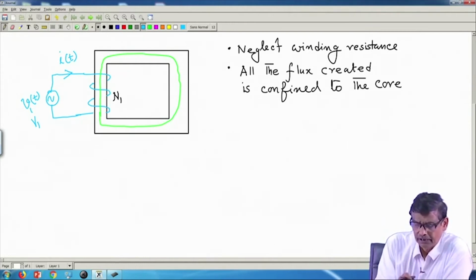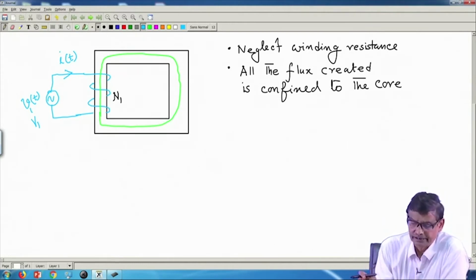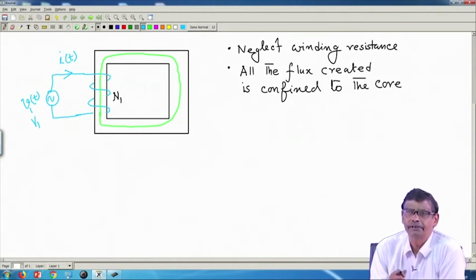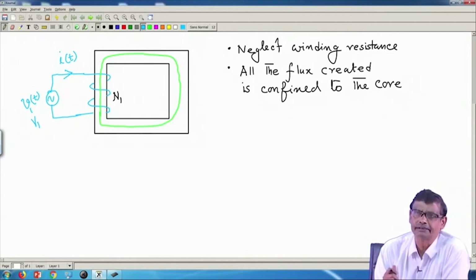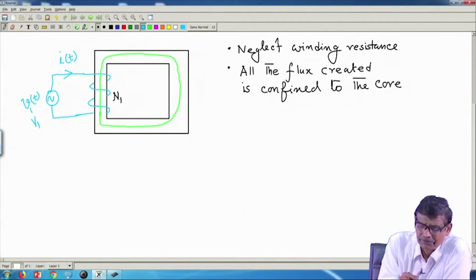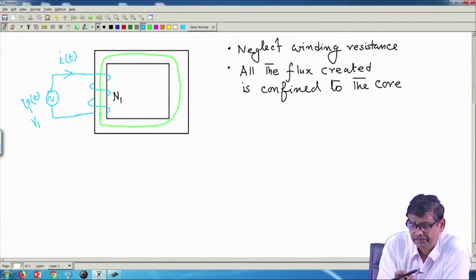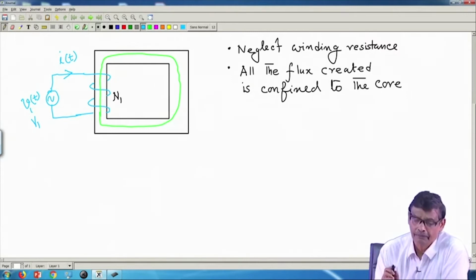Look, there is a coil having no resistance, and therefore, this coil will perhaps act as an ideal inductor, and therefore, it will draw some current 90 degrees lagging. The value of the current will be decided by the inductance of the coil.